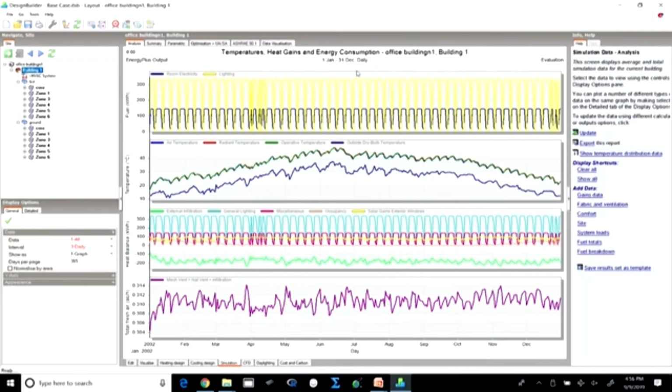For any green building rating system compliance, whenever we want to show the energy performance of a building using simulation software, we have to simulate the building for an entire year on an hourly basis. Hourly simulations are required. So, all the 8760 hours will be simulated here, and on the basis of the simulation, the comparison between the proposed case and the base case will be shown, and the compliance will thus be achieved.